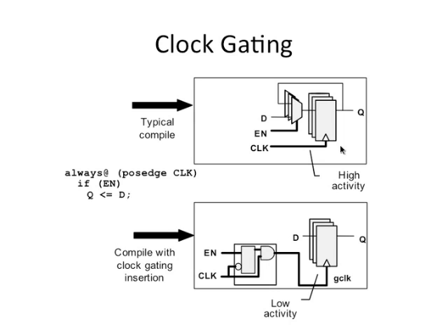So every clock edge, I am sampling the input to the output, but the input has the same value as the output when the enable is low. So only when enable is high, I pass in the new D value which gets sampled. But you see, this is not a very efficient way from a power perspective, because your clock net is unnecessarily switching here. It's toggling the clock input of all the flops, even though I didn't need to.